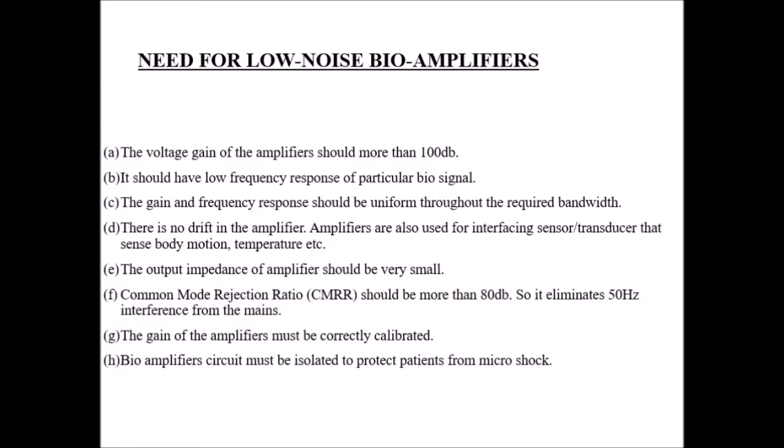Next, the gain and high frequency response should be uniform throughout the required bandwidth, and there is no drift of the amplifier. Drift means the output value should not gradually get reduced. It is due to some external influences, for example body motion, temperature, and interference of EMI waves also.